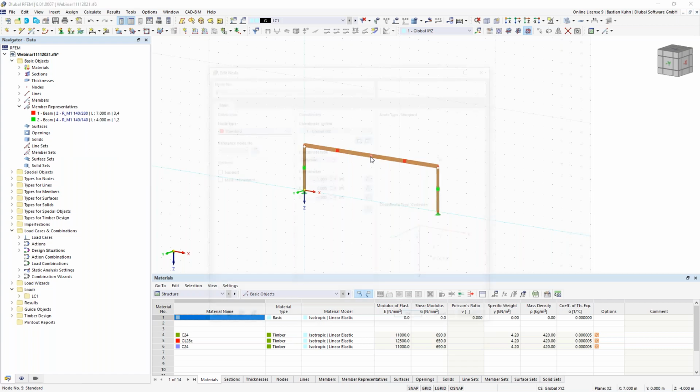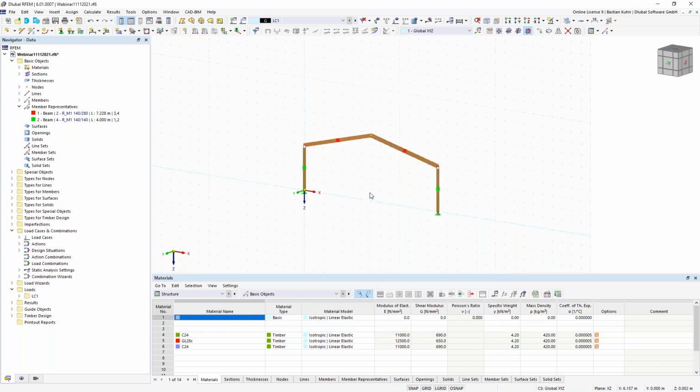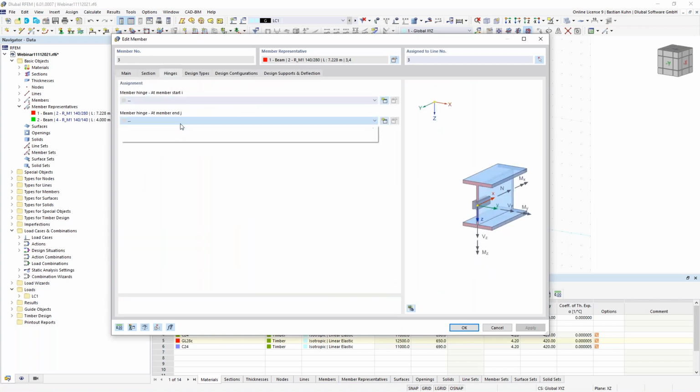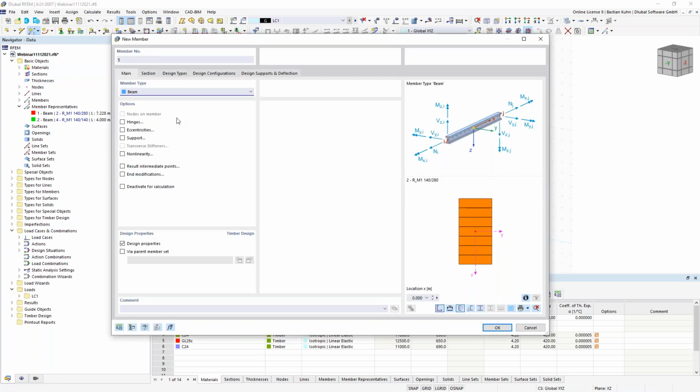So we want to have a roof angle of 13 degrees. That gives me some height, and here at one edge I also want to have a hinge, and therefore I'm defining it there as well. So now we need the bottom girder of the little truss that we are designing, and in this case I'm using a truss type, because all the other elements that I have should actually not be loaded by bending, so I can use the truss type in here.